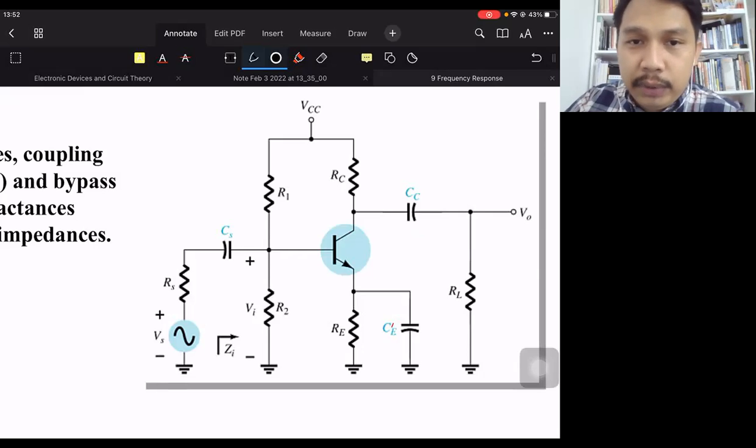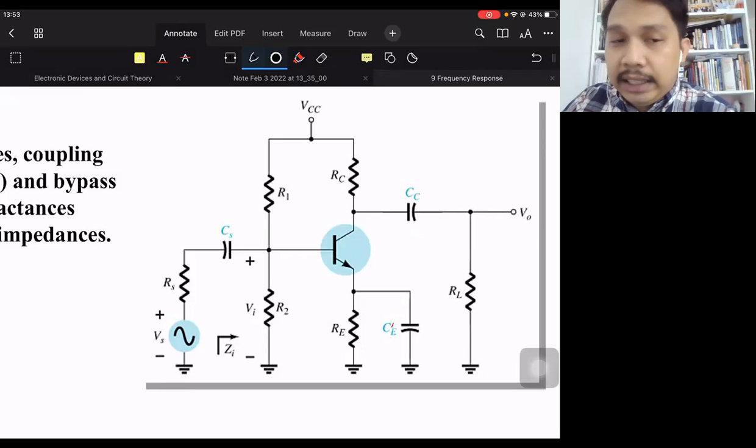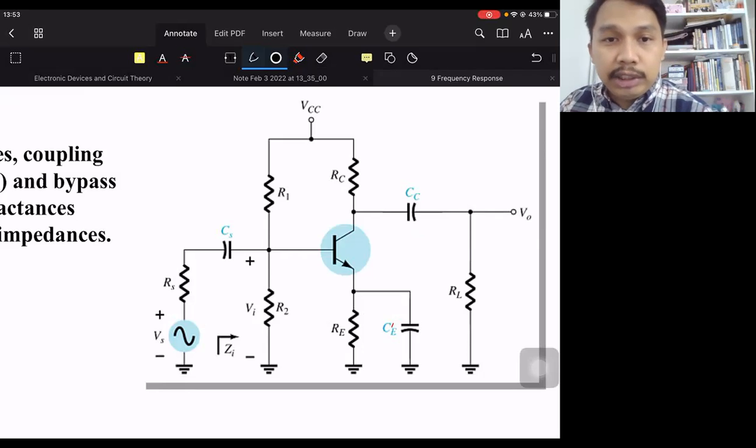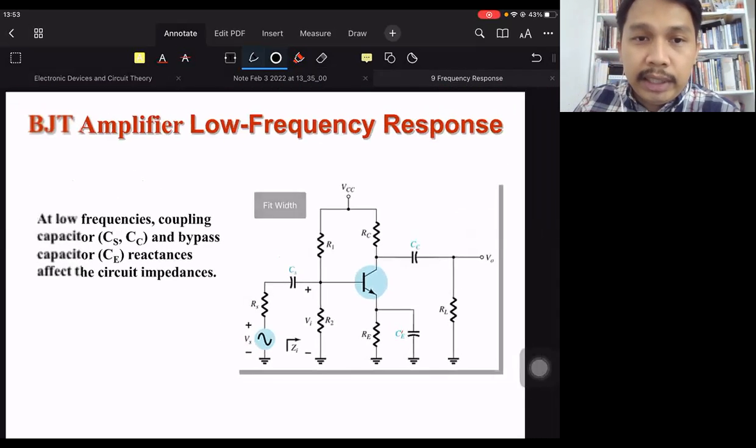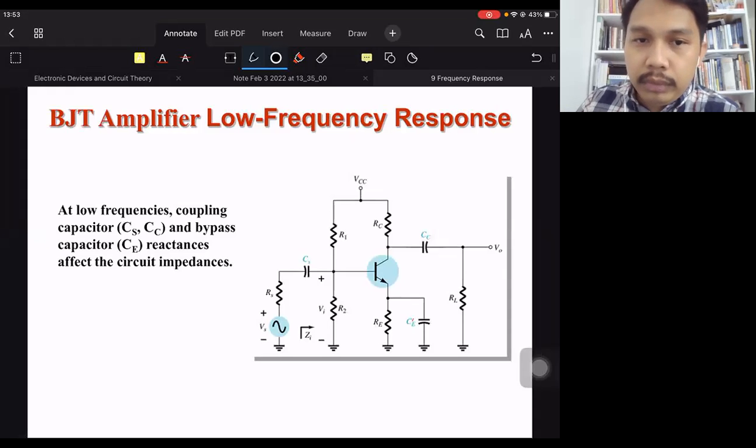We will now investigate the frequency effects introduced by the larger capacitive elements of the network at low frequency and smaller capacitive elements of active devices at high frequency. Because the analysis will extend to a wide frequency range, the logarithmic scale will be defined and used throughout the analysis. In addition, because industry typically uses a decibel scale on its frequency plots, the concept of the decibel is introduced also. The similarities between the frequency response of both BJT and FET permit the coverage of both topics in